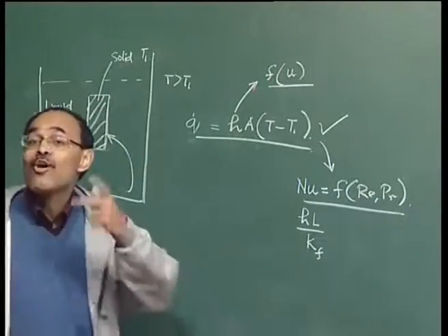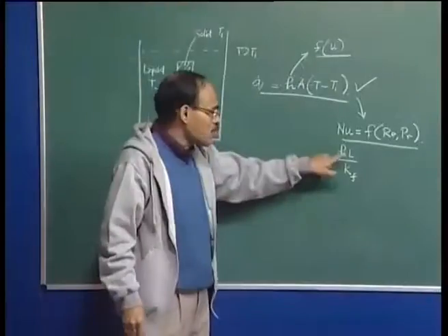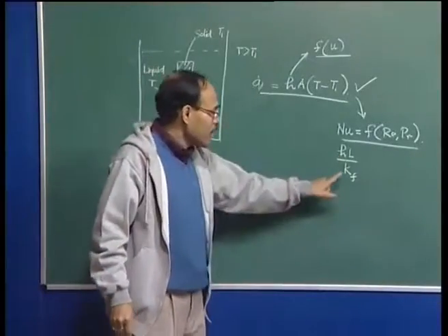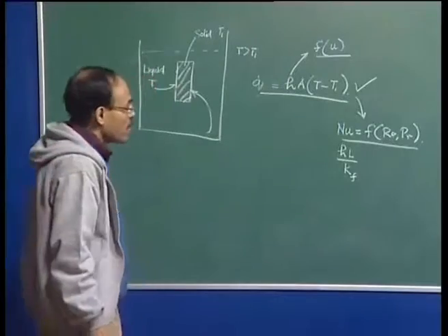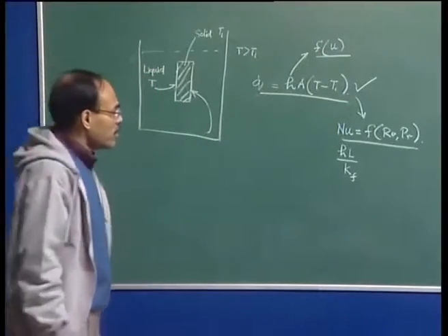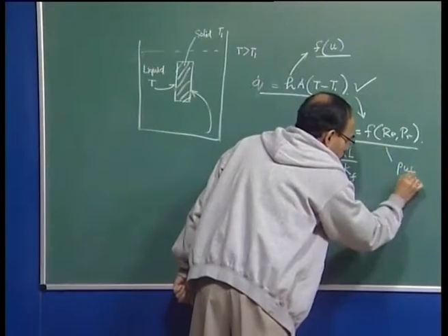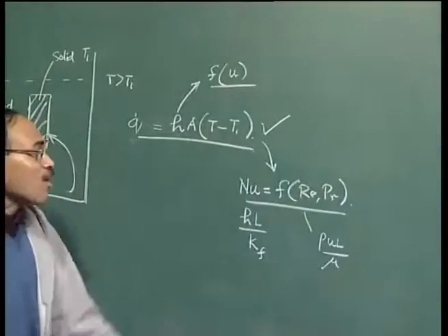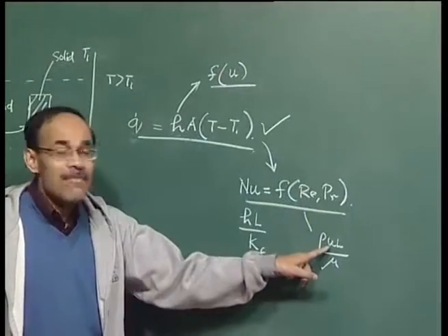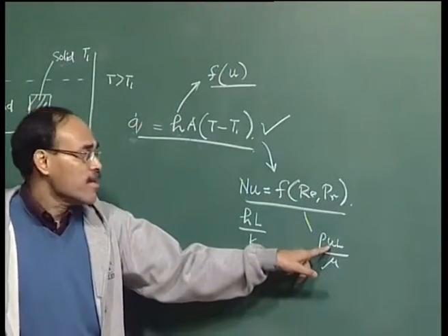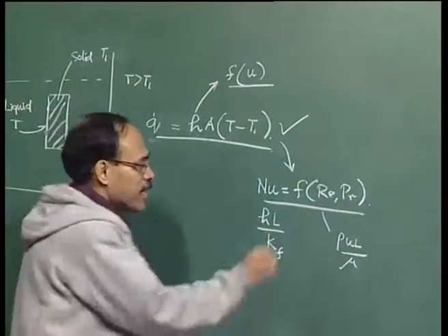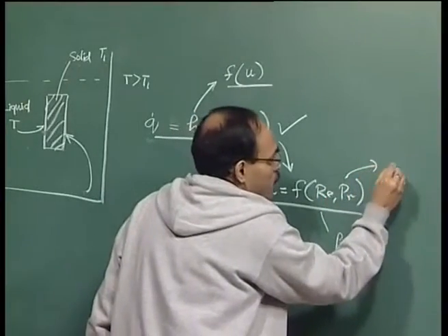On the other hand, if you are talking about Biot number, which looks similar to Nusselt number, there the thermal conductivity is the thermal conductivity of the solid. Reynolds number, as we all know, it is... So, Reynolds number can only be calculated provided we have some idea of the flow, and Prandtl number is again a thermophysical property. So, it is alpha.